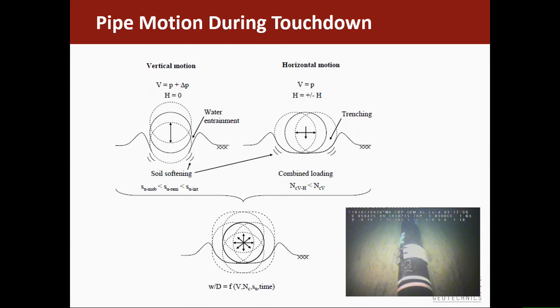But the important thing here is that the pipelines, as they're laid, if there's a vessel motion, they're moving up and down as they touch the seabed. If there's any horizontal motion, which could be currents, that could move the pipeline side to side. So you end up with this, that's your pipeline, but it can be moving around anywhere within that sort of envelope.